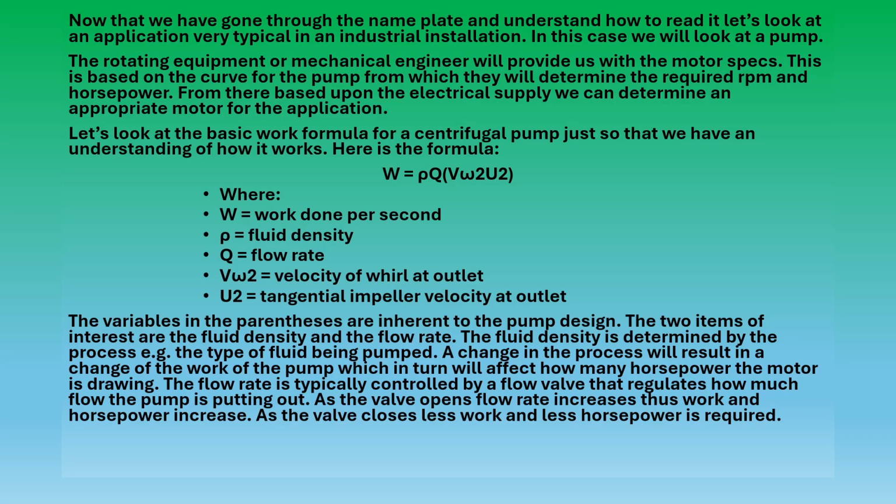Now, typically, when you have an existing pump, let's say, and you got an existing motor, and the motor's been running fine for a year, and then all of a sudden it starts tripping out on overload. Well, the very first thing we want to look at, has there been a process change? Have they changed the fluid viscosity or density that pump is handling?